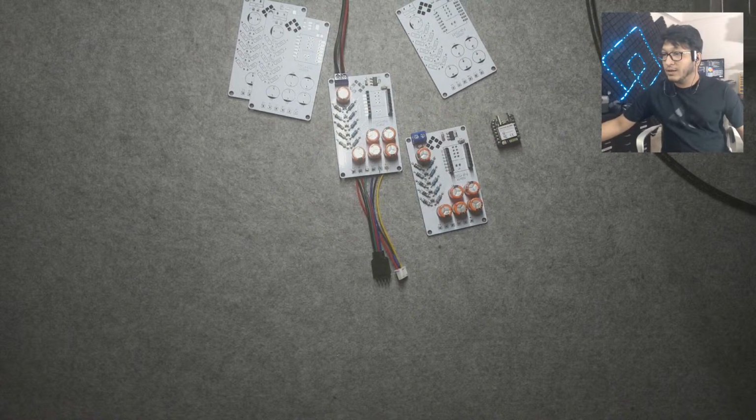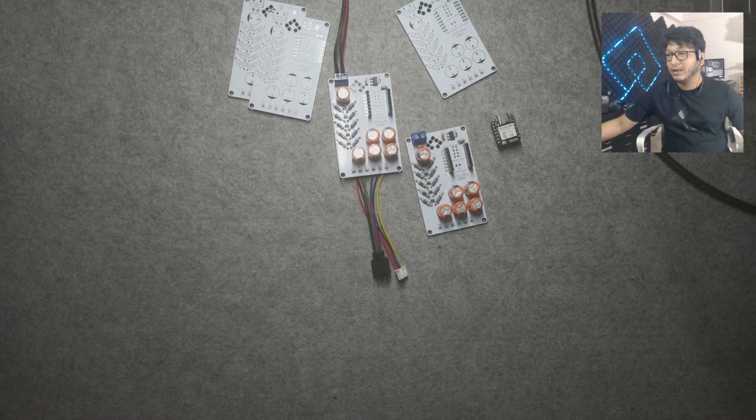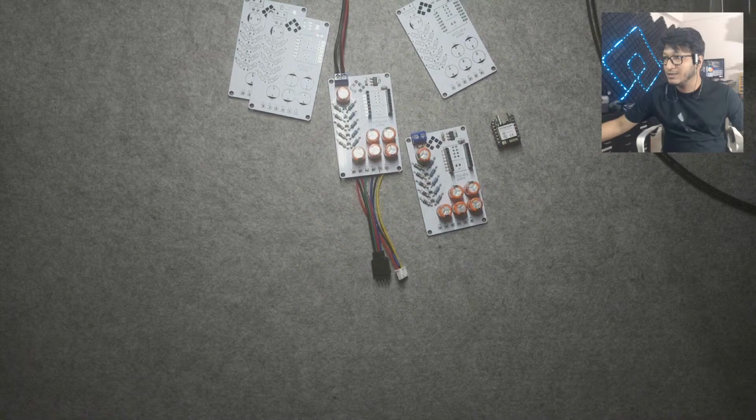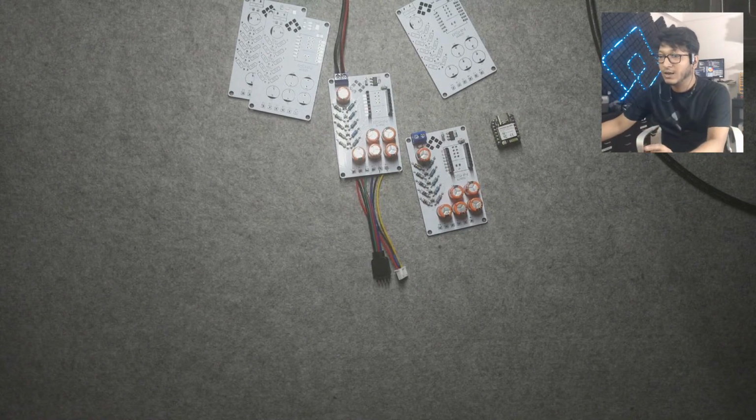Right. So I went with a 2-layer board. If I make the top layer go away and show the bottom, the tracing is a little bit hard, because I have to go here, then trace through this and come back out with that. It would have been much easier to lay them out closer together with a 4-layer board, because there would have been much better crossover points.